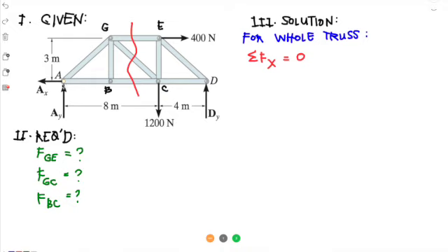That's AY and AX. Again, we need to verify if our assumptions for the directions of these unknown support reactions are correct. So if we will do in our mind summation moments in A, let's hold A right here, and identify the moments.